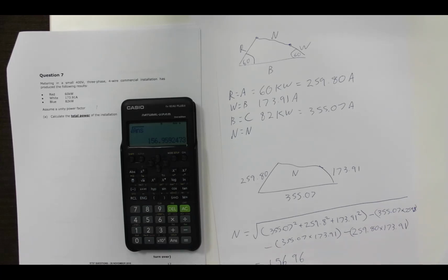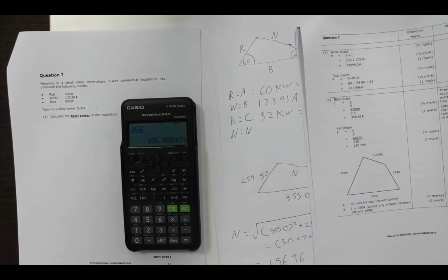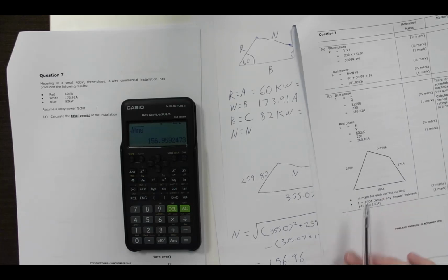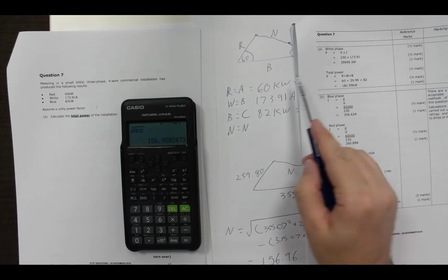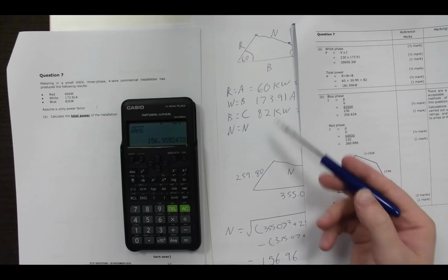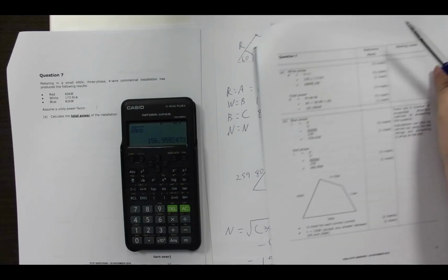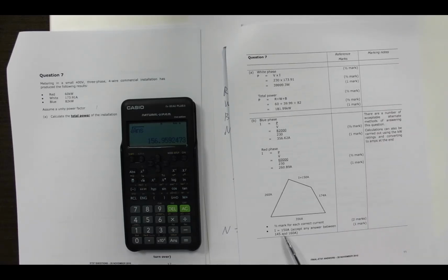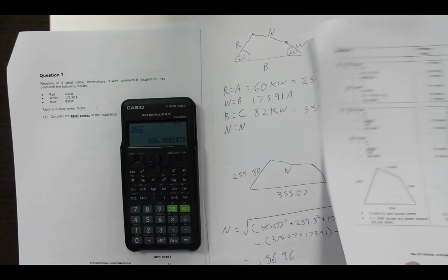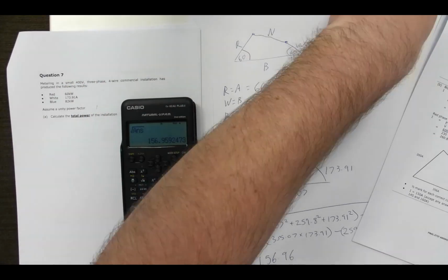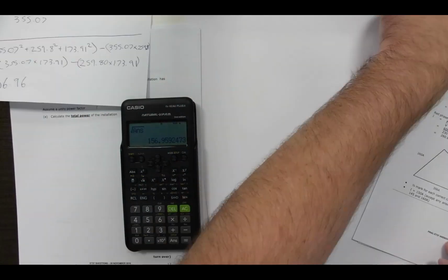Looking at the answer sheet, before we got closer to the 150 amps, because we didn't have rounding issues from writing in the values, and when you're squaring. So that's one of the reasons why they have I equals 150, and when we calculate it this way, we got 156.96, even though that's less accurate than our previous calculation, because we had to round.